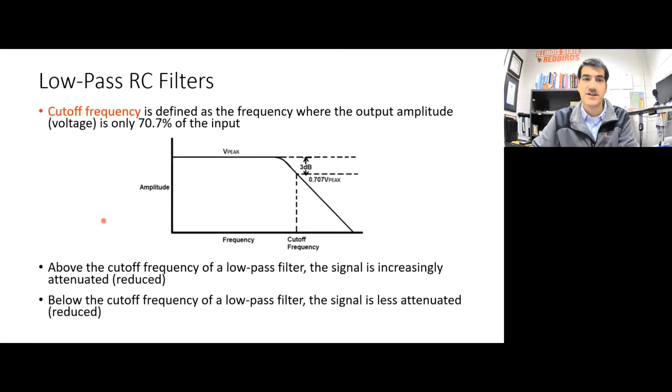All right, now we'll talk a little bit more about cutoff frequency, because I don't really like saying "blocked," since the cutoff frequency is kind of misnamed. It's not like it passes frequencies up to a certain point and then all of a sudden, boom, it blocks all the frequencies above that. It's hard to design a circuit that does that. Certainly this type of RC low pass filter doesn't do that.